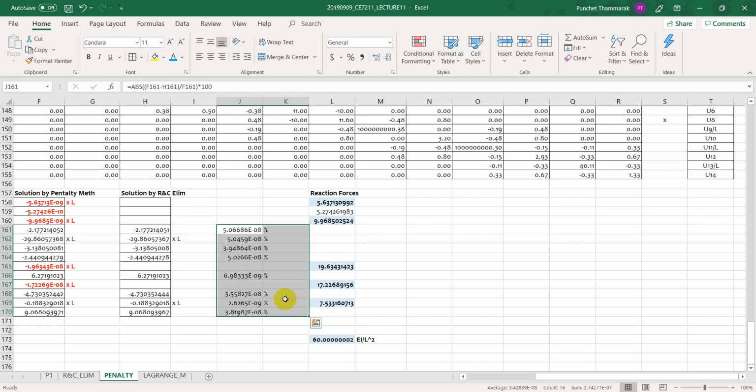Something might be the concern generally for the structural analysis. The problem that I mentioned yesterday about the large number that you put as the penalty spring stiffness will make the condition number of the matrix quite large, and that means you are quite like a singular matrix. You cannot inverse it. Okay, the problem like that comes up, but you don't find it in general for structural analysis.